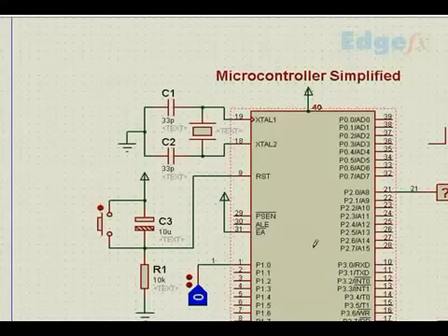How do we do it? We use a cross compiler. We call it a compiler. Let's not get put off by the word compiler. It's nothing but a simple software, and it could be Keil software. In that Keil software, once we write that program, we convert it to the hex format, and that hex format, through the programmer, we use a programmer. This is the IC. We take this IC to a programmer, put it on that programmer, connect it to the computer, and then download that hex format onto this microcontroller. And then it becomes a product to be used. Otherwise, it cannot be used.